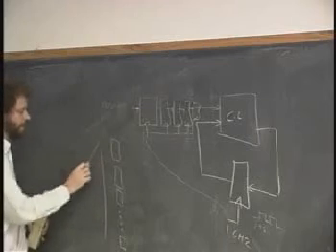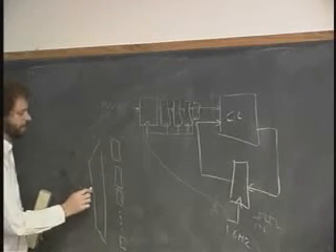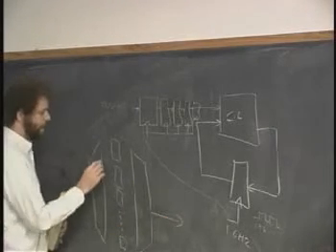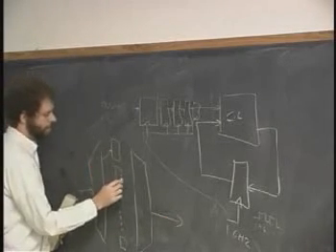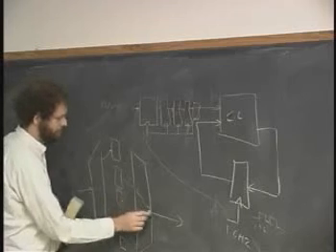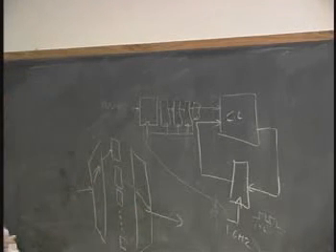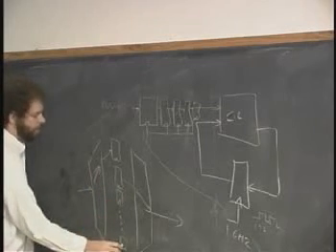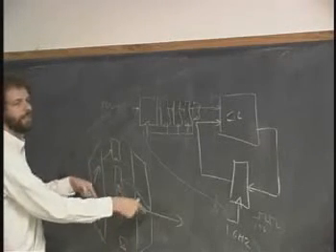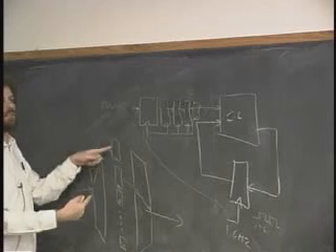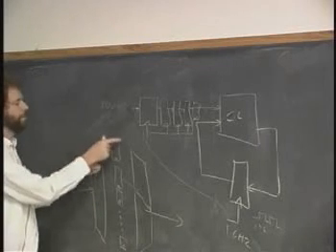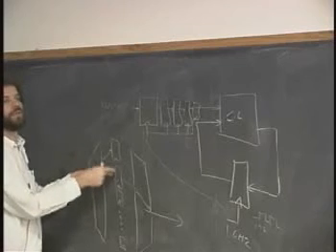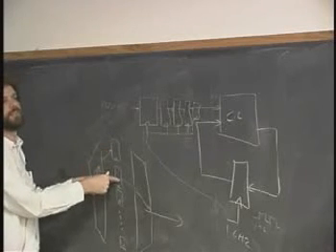And I can have a decoder over here and a multiplexer over here, and I can basically be doing a round-robin scheme like this, where these are only clocked at a 100th of the rate, and I basically go around and around like this, and each one of these takes a part of the job and takes 100 billionths of a second to get this done, but the next job is given to the next one 1 billionth of a second after it's given to this one.